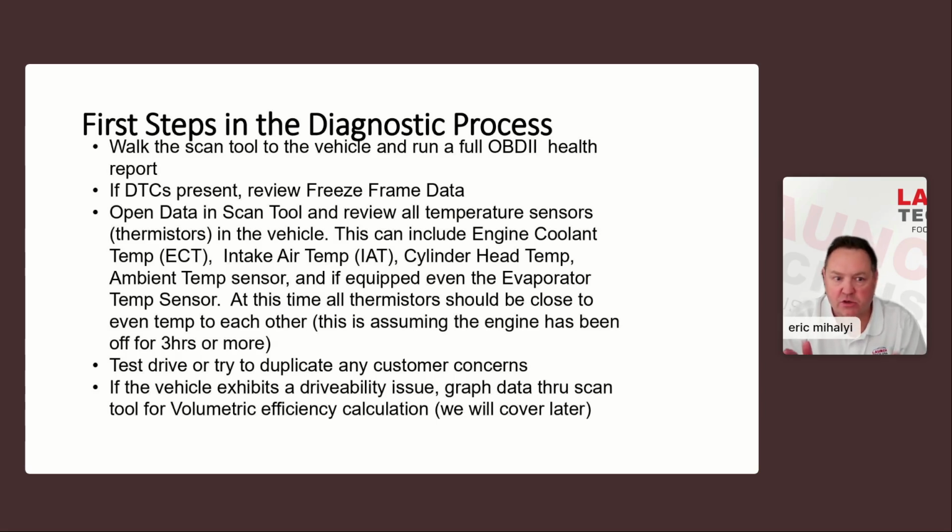And now there's nothing actually wrong with the car from the misfire standpoint and parts associated with it. It's the way the ECM is programmed to fight that overheating process, right? Limp mode, if you will. Okay. Same thing, intake air temperature sensor, right? You possibly have one that's really high. Of course, that can affect the running conditions of the car.